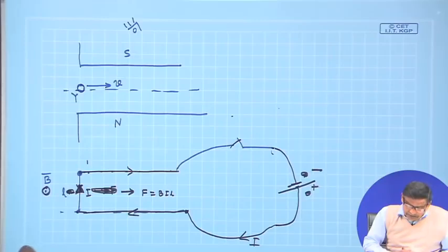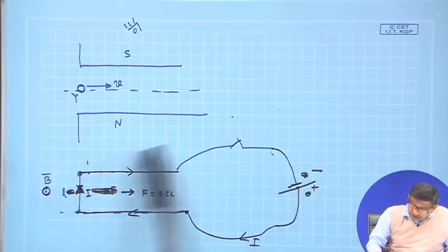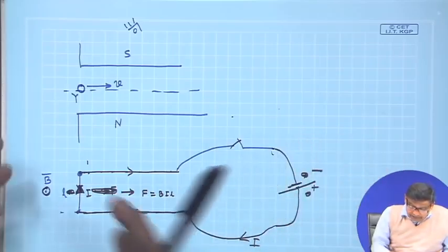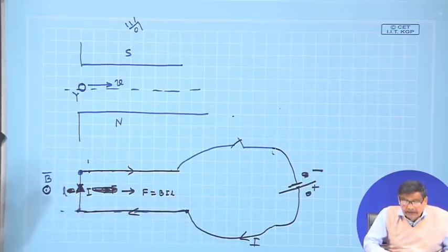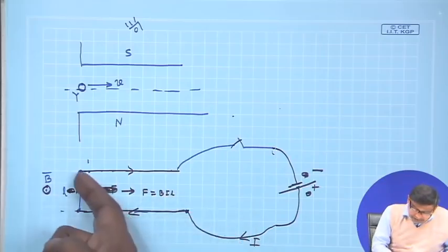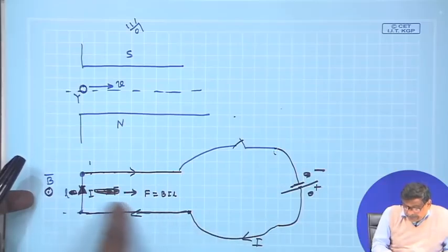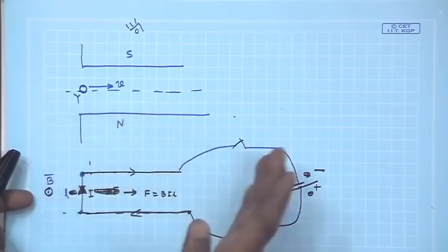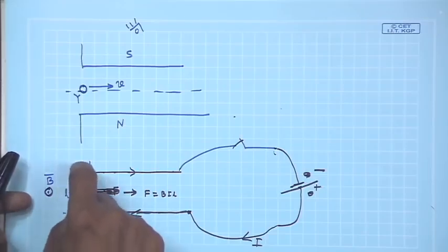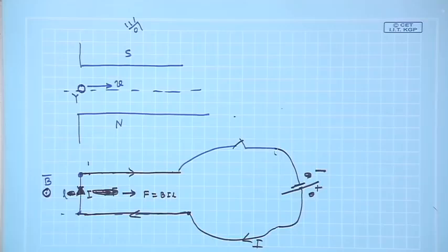But one point must be understood very clearly, if it starts moving, the magnitude of the current, I am not sure whether this E divided by total R of the circuit will be the magnitude of the current. Because the moment this fellow starts moving, I know that a conductor moving in a magnetic field with some velocity will have some induced voltage in it. Therefore, this conductor itself will become another source of EMF. Therefore, to find out the currents in this circuit, not only this EMF will be acting when this conductor has started moving, but also another EMF which will be generated across the 2 points of this conductor. These two together divided by the impedance or resistance of the circuit should decide what will be the current in the circuit.